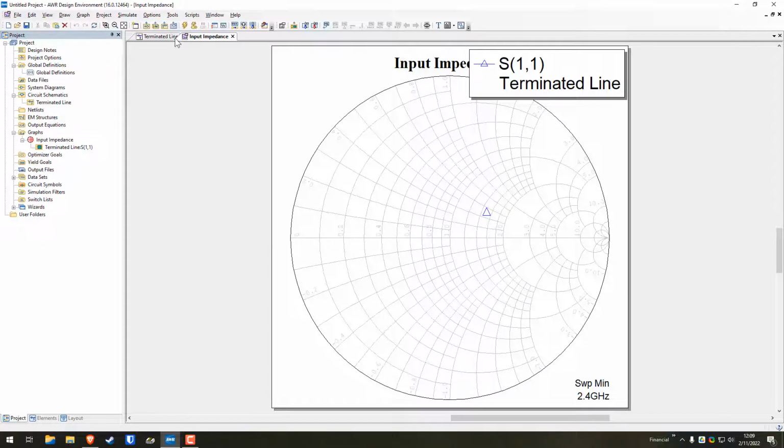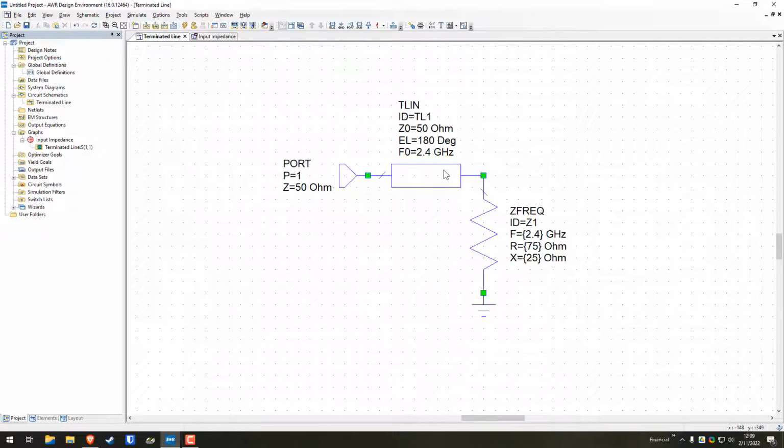And the reason why that is, because as we know from microwave engineering, microwave circuits, we have a half lambda feeding line here of an equivalent impedance to the port. So this feeding line is 50 ohms, it's 180 degrees. So it basically just pulls this load impedance to the port. So the input impedance that we're looking at in here, if I could draw,